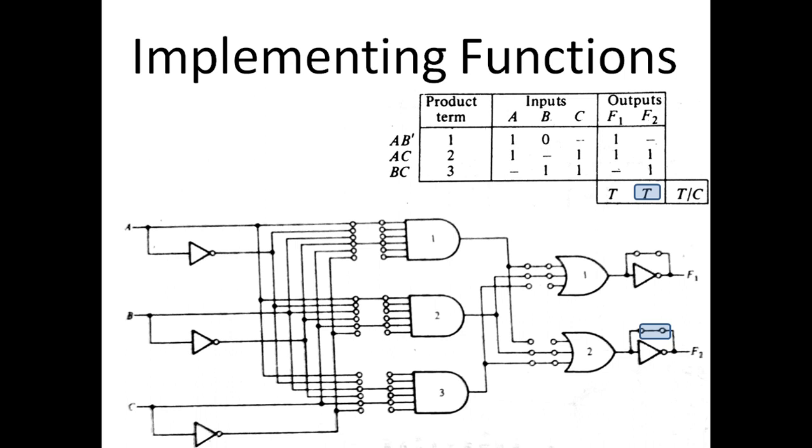So we had 3 product terms here, 3 AND gates, which is the value of k, and we have 2 outputs or 2 Boolean functions. So we had 2 sum terms and 2 outputs. And then by looking into this program table, we programmed this programmable logic array.